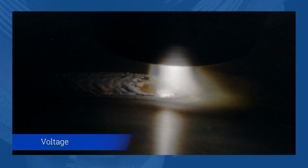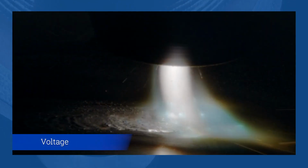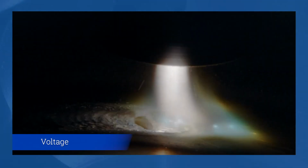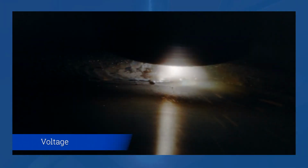Now let's talk about arc voltage. This is another key variable. Here we have the voltage set properly. Now we're going to raise it up too high. It's pretty obvious. We're not getting good bonding. We're seeing some sparks. We've lost some of our shielding. Now let's go too low. Now we're crowding the arc. You're going to damage the torch. You're not making a good weld at all.